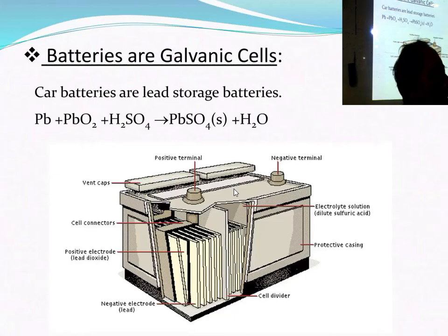Earlier you thought this is the total surface area of the plate. Now the surface area of the plates is getting damaged in different places. So obviously the overall surface area will decrease, no? So the capacity is going down. Voltage is constant, but capacity is going down. As I told you yesterday, about capacity and voltage: voltage depends on how many plates, and capacity depends on the size of the plates. If you make the size of the plate larger, the capacity of the battery will increase. And if you increase the number of plates, the voltage of the battery will increase.